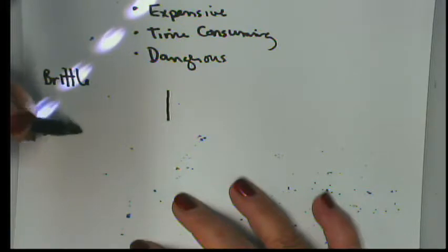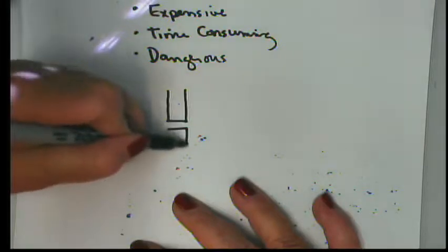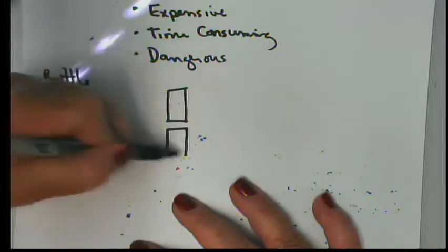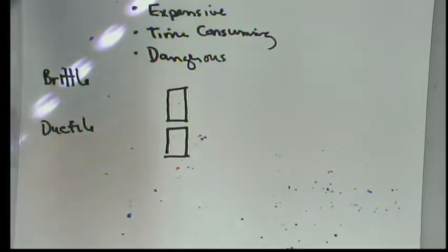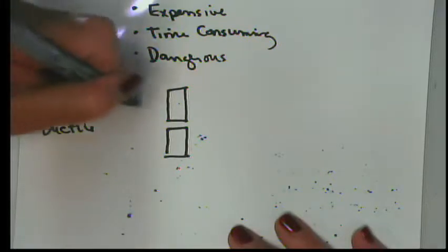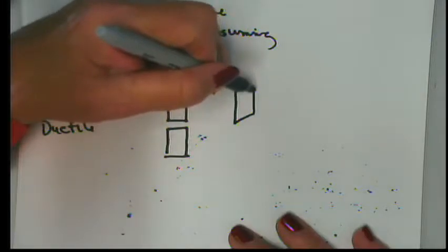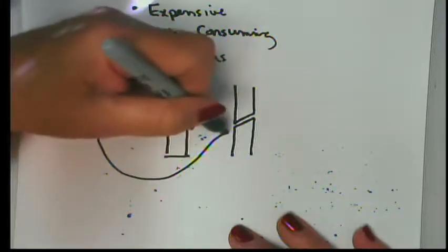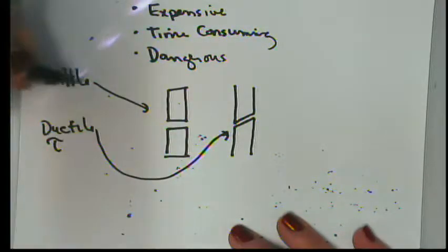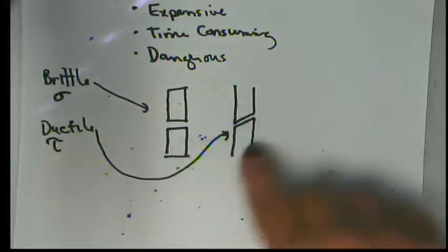And what it means is brittle things tend to fail catastrophically, and they also tend to fail in normal stress. So that means you pull on them and they come apart, and the surface of breakage will be pretty square, like this. Now, if, on the other hand, something that is ductile fails, it will tend to fail more on a 45-degree angle. And that's because it tends to fail on shearing stress. And in the real world, of course, you have both normal stress and shearing stress. But in general, this is sort of indicative.